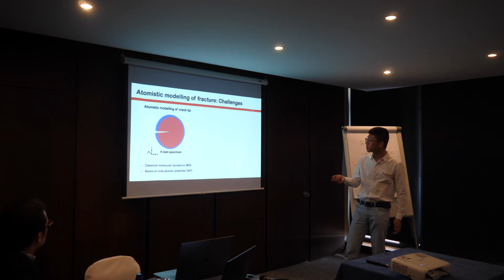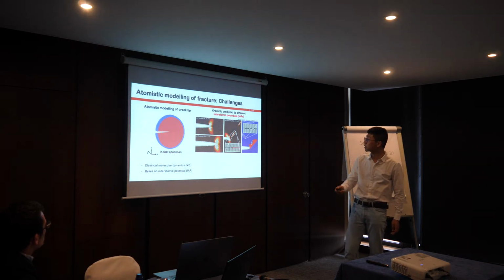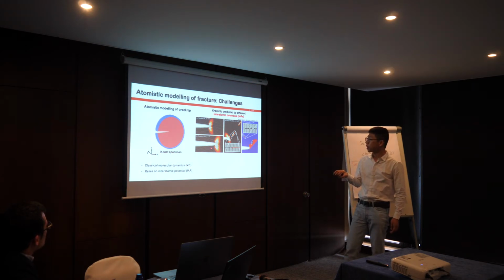So here we use this specimen, where the x direction is the crack propagation direction, y is the crack plane, and z is the crack front. These blue atoms are boundary atoms, so we apply the displacement solved by anisotropic linear elastic fracture mechanics to the boundary atoms and relax the system to let it evolve. So there already exists some classical molecular dynamics modeling of crack tip response.